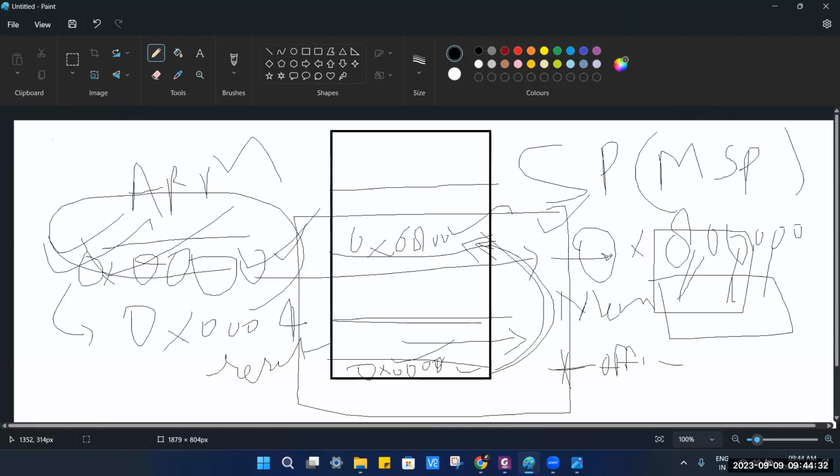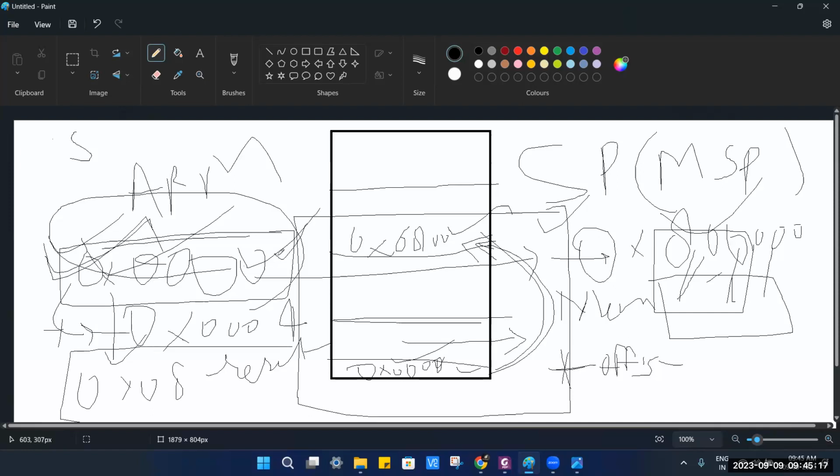Yes, the generic flow, at a higher level. I will also check this and tell you. But the basic understanding of how this is happening is, once the power-on reset happens, it will check this address. As every company is doing memory aliasing, once you try to fetch data from this address, it will check what is set, meaning they want to fetch this value from here. So this would get replaced with 0x0800, and mostly companies are doing it with an offset value. They will add something here and this address would become that address, and the same aliasing applies above also. So if you want to read 0x0000, it will read 0x0800. If you are reading 0x0004, the same offset value will get added and it will become 0x0804.